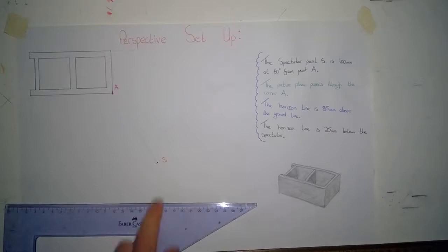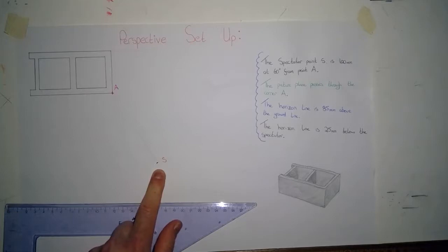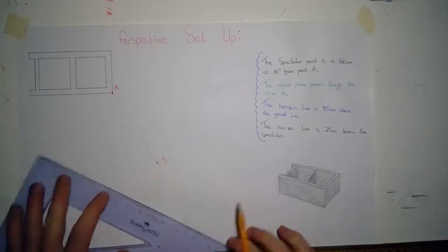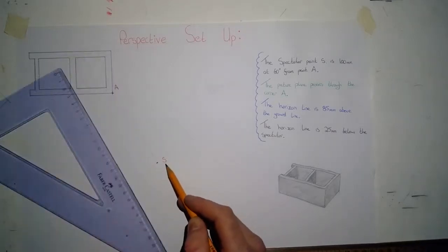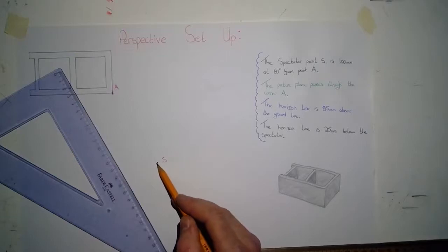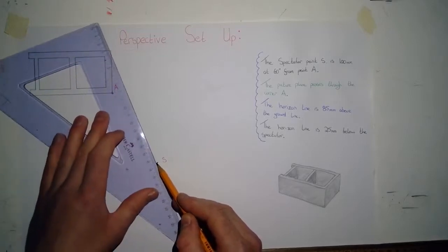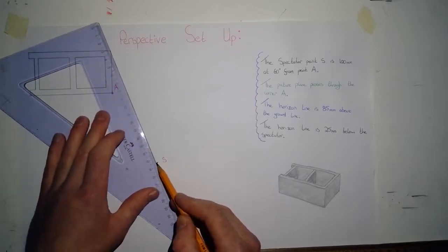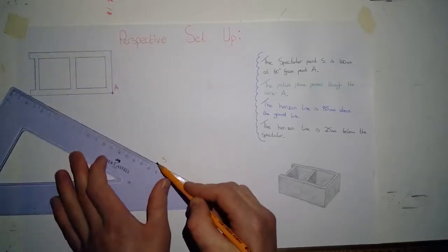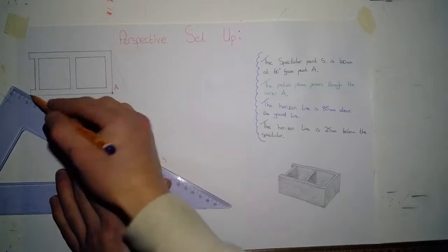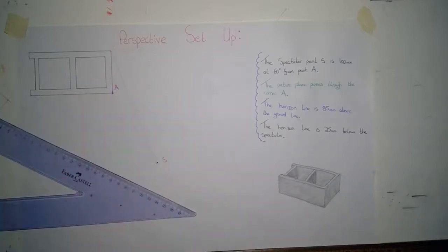So the next step, when we have our point S or spectator located, is to get what's called the sight or the lines of vision. Basically, what these lines of vision are is, if I was standing at this S point or the spectator point, what are the most extreme corners of the object that would be in my vision. So this would be one of our corners, and the outside here would be another corner. So that basically is my farthest points of vision.